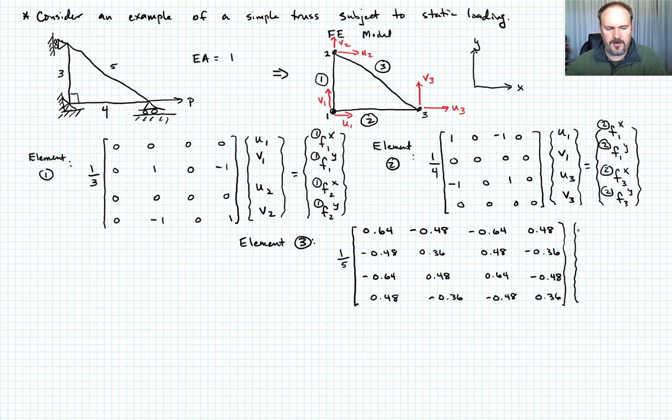For element 3, the displacement terms are U2, V2, U3, and V3, equaling my force terms F2x, F2y, F3x, and F3y. Again I'm putting the pre-superscript of the element, so these are for element 3.